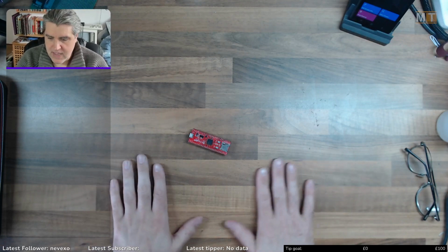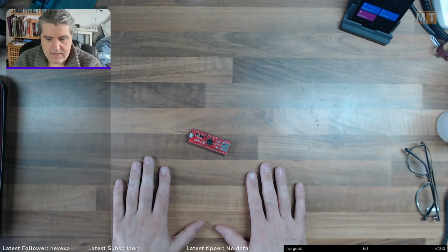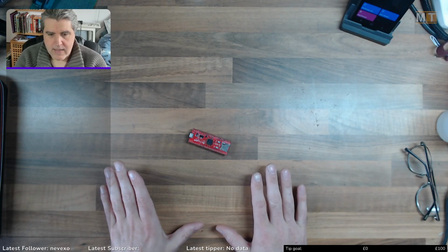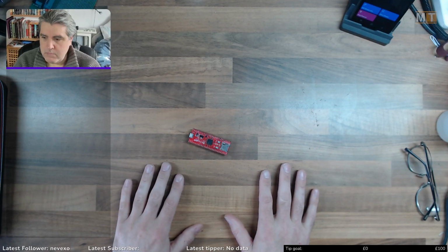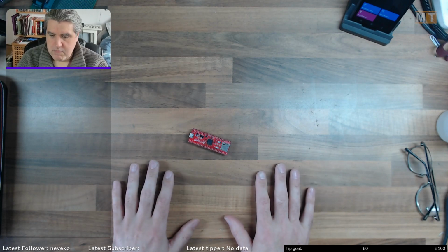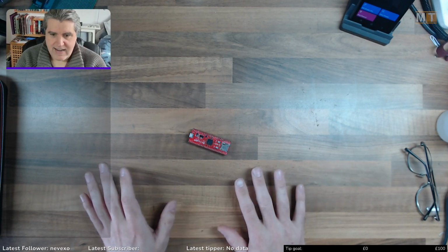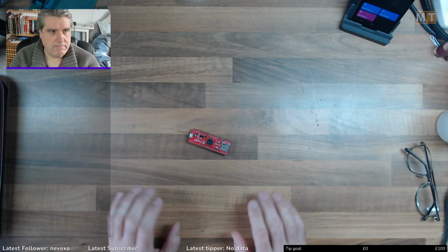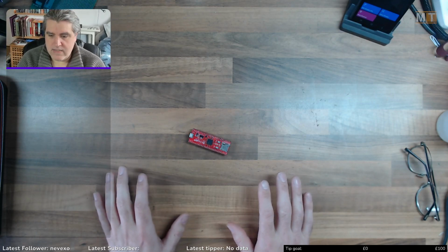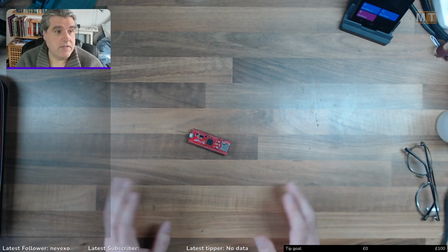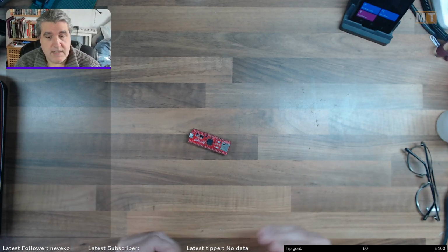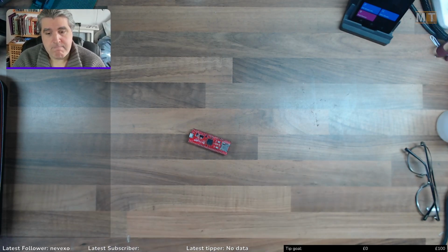So what I'm thinking is a slightly more complicated system whereby I can read and write over the USB. Anything I write gets written out as if it was a microprocessor bus. Anything I read performs a microprocessor bus read, captures the data, and then returns it to me.